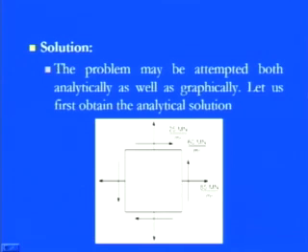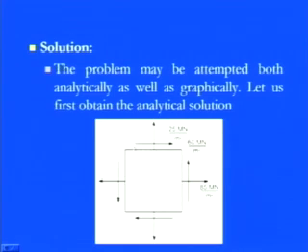On this element the axial stress sigma x is tensile, 85 mega Newton per meter square. Perpendicular to that is sigma y, 25 mega Newton per meter square. The shear stress components always tend to rotate this object clockwise, with a value of 60 mega Newton per meter square, and it acts only where this 25 mega Newton per meter square is.